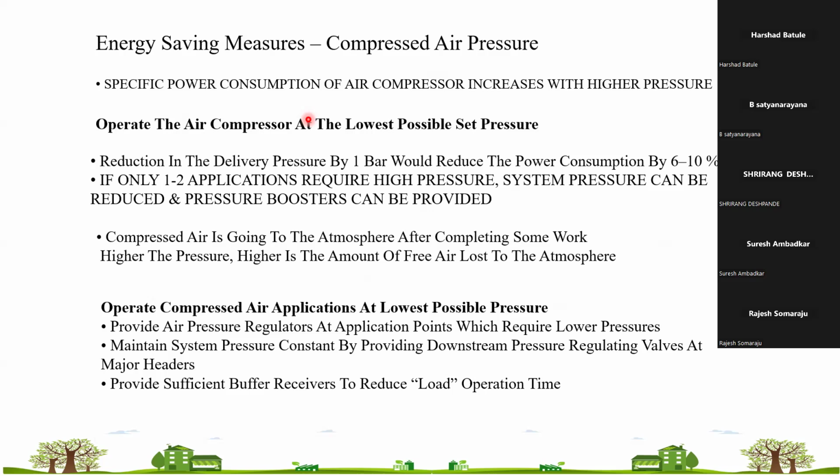So this kind of mistake does happen in industry. Those can be rectified. You can separate out those two utilities, or you can design a higher cooling tower size. That can be taken as a precaution during your energy audit or during the designing of any system.